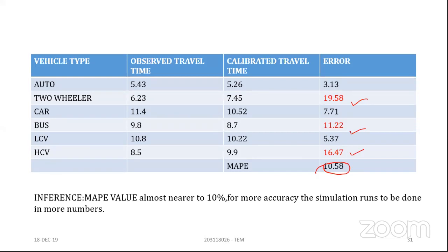Initially, we know your geometric field characteristics. If you increase your geometric characteristic by 3 meters extra, how the performance is changing, that analysis also you can get in an output. Still, if your study requires a flyover, there is an option of constructing a flyover in Visum software. On the major road you can construct the flyover and change the movement of the vehicles, and again you can perform this same analysis and get the safety of that particular location by providing the flyover.